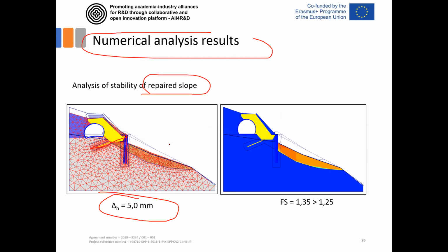In this simulation, the conditions are changed in comparison to the real problem. It was actually done that in the first phase, the piles and ground anchors were constructed. And after that, this reinforced earth slope was constructed as a surcharge that introduces some lateral displacement and bending moments in the piles and tension in the anchors. So the phases were changed in comparison to the real-time situation.